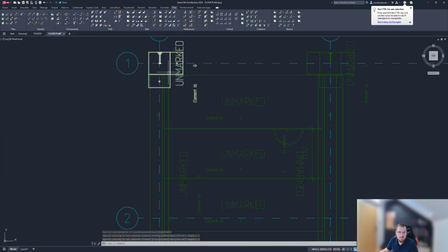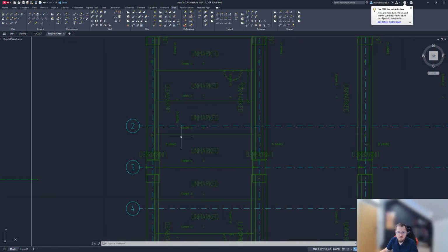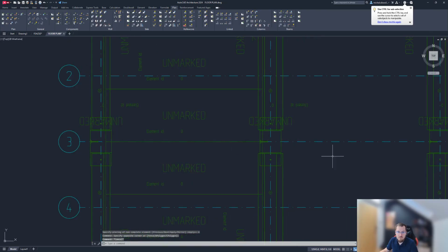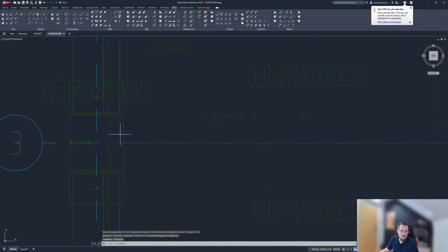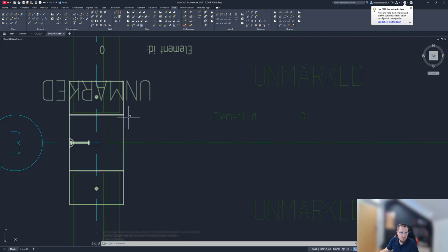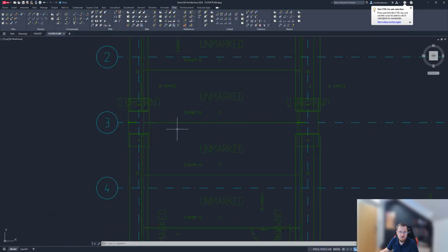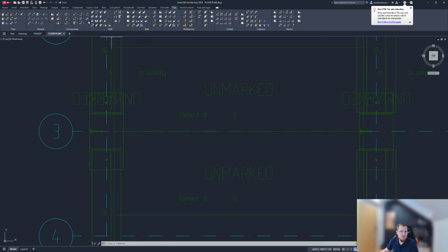done. What we will do now is we will edit those two hollow cores very quickly to make sure that we are actually cutting around the column that we are passing through here. And we can do that super quick with our recess tool. There's a draw recess feature, where you can manually draft it over and use that like a rectangle or a polyline to cut that opening out.